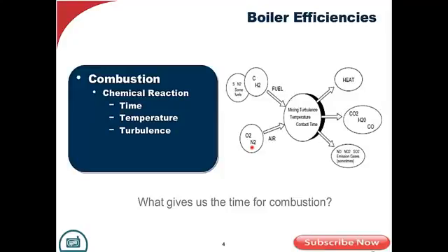So then we have a burner that takes these elements, the chemistry goes on, oxidation occurs, and when that oxidation occurs, what we get is heat that comes out, the BTUs. We have some CO2, carbon dioxide, which some will refer to as the global warming gas. We have some water, and we have carbon monoxide, possibly. We try to keep that to a minimum, and we'll talk about that later. We might also have some nitrogen oxides and some sulfur oxides, depending upon the fuel. These are emissions that come out of this oxidation process that we have to contend with.